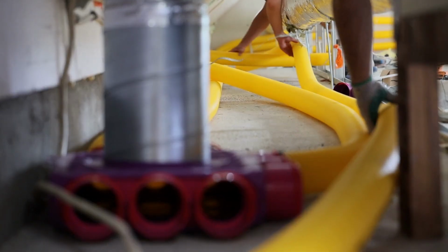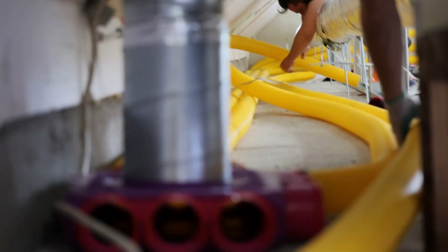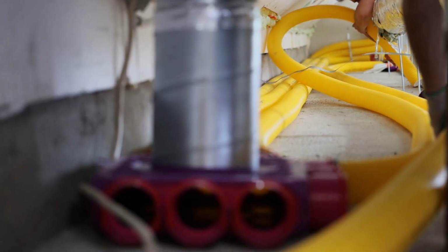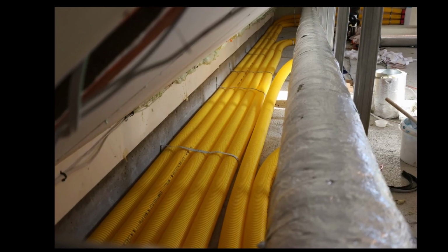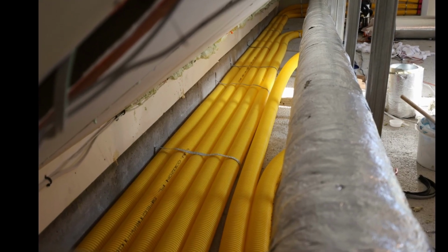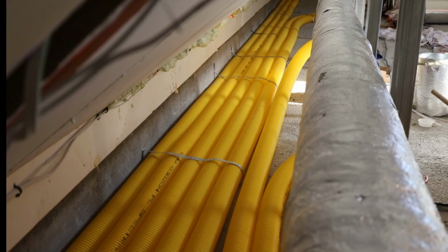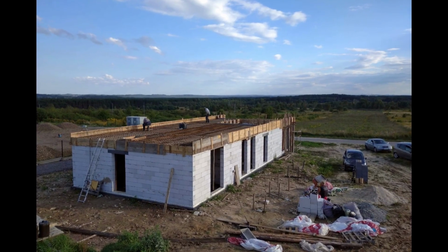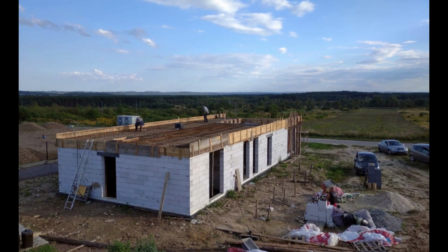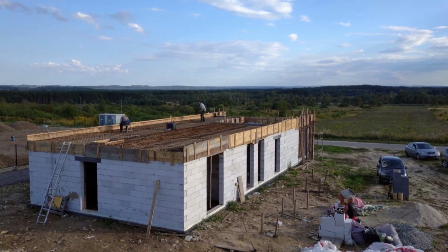The disadvantages of this approach certainly include a reduction of usable space in the attic, an increase in the thickness of the floor layers on the attic level, and the necessity of drilling through the reinforced concrete ceiling slab. Not to mention the obvious deterioration of the load-bearing capacity of this slab due to all the reinforcing bars that would be cut when creating openings. I definitely recommend designing the entire system beforehand. Ideally have it all thought out when the walls are being built and the ceiling slab is reinforced.